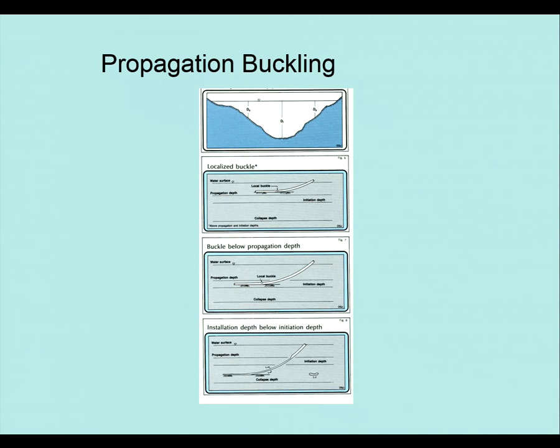So once you've initiated the buckle, it will propagate. If it's in a depth below the propagation pressure water depth, then it'll propagate till that water depth equals the propagation pressure, and then it'll stop. But it will run on a bit, which we won't go into. So that's the propagation.